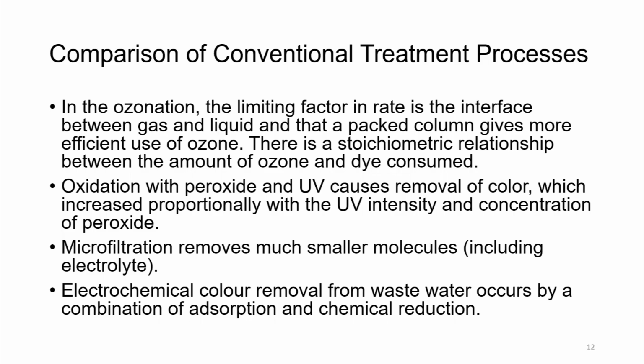Now, if we make a comparison of conventional treatment methods, in the ozonation, the limiting factor is the rate at the interface between gas and liquid, and a packed column gives more efficient use of ozone. There is a stoichiometric relationship between the amount of ozone and the dye consumed. So, here a large amount of ozone has to be used because it is taken into stoichiometric equivalence.